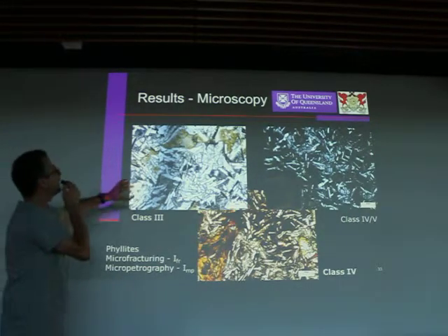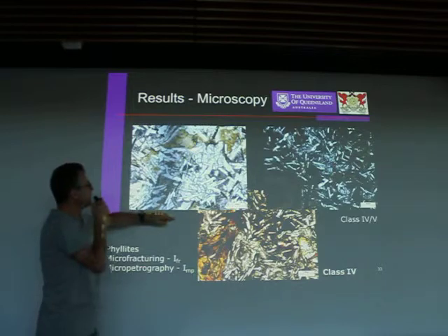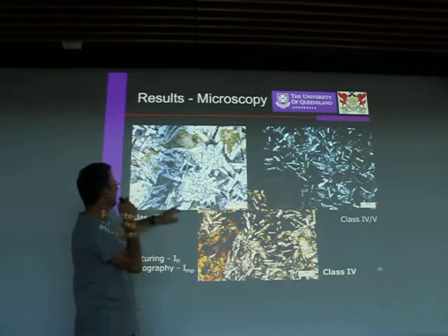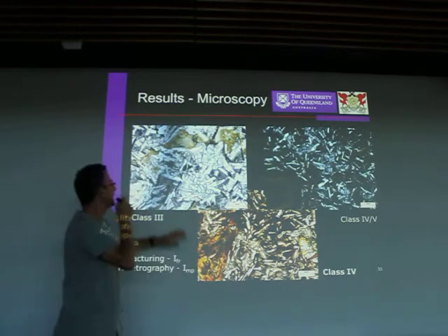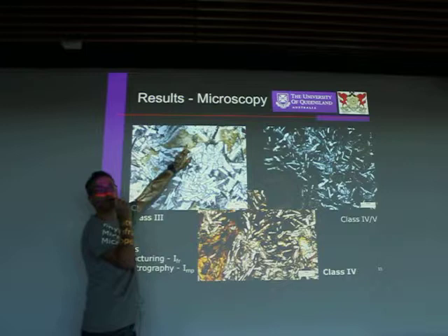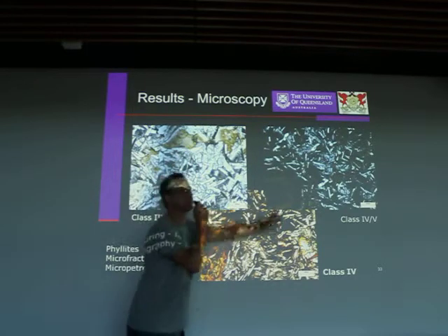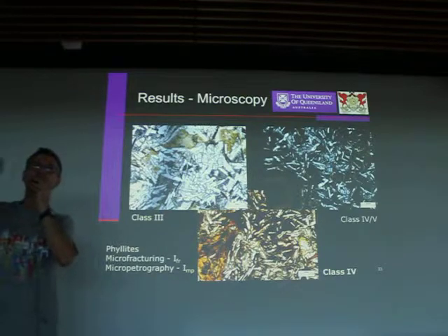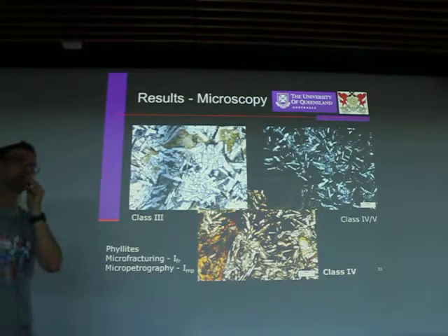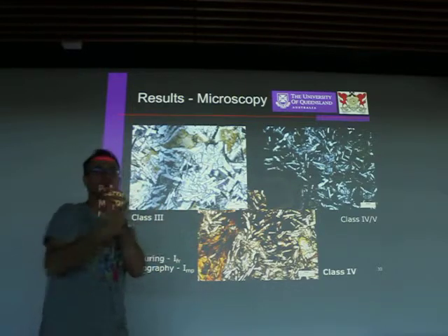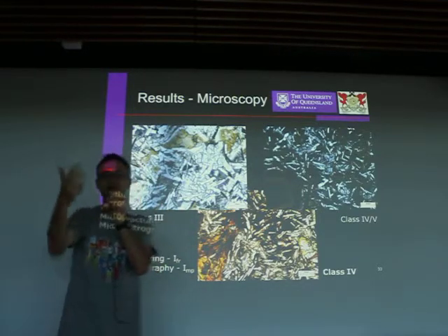Here, finally, are the examples from the basalts, and you can see lots of feldspars, and again, microfractures, and again, an increase in the clay mineral content and the iron oxide content with the weathering. So it's very important to connect this mineralogy description, mineral characterization, with the physical and mechanical tests in order to understand the results that you get from it.